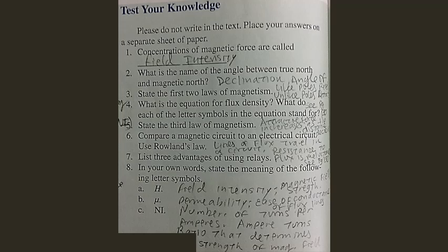Also, there is resistance to the magnetic flux in a magnetic circuit. This resistance to magnetic flux is called reluctance. Reluctance is measured in Gilberts per Maxwell or in ampere-turns per Weber. So 1 ampere-turn per Weber is sometimes called a rel.